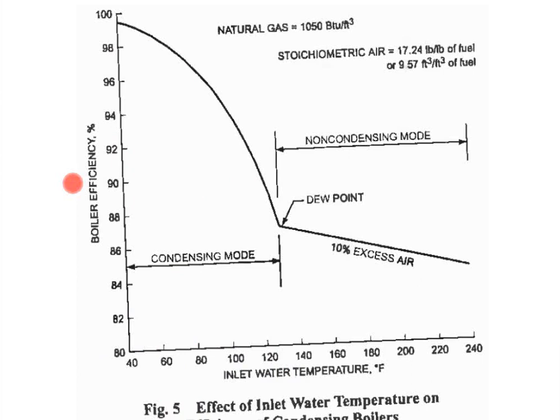Now, if you've got a non-condensing boiler, you can't allow that condensation to happen. You're going to have to put a mixing valve on there in order to get the cool 100-degree water for your radiant system, but that doesn't really help your boiler efficiency. So as soon as you say you've got a radiant floor system or a snow melt system, a condensing boiler becomes an absolute no-brainer, and you would use that in all situations unless you happen to have another boiler there and you're just stealing waste heat off of it for some reason. But anytime you're designing anything new, if it's radiant, you definitely want a condensing boiler. Putting a non-condensing boiler in is going to cost you more in mixing valves than it would have been to just buy the condensing boiler up front.